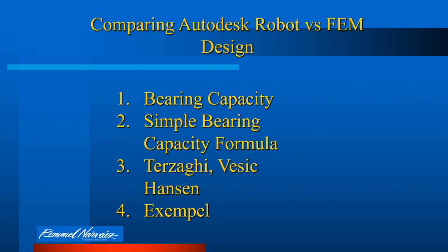To analyze spread footings for bearing capacity failures and design a way to avoid such failures, we must understand the relationship between bearing capacity, load, footing dimensions, and soil properties. So we are going to look at these blue points about bearing capacity: the simple bearing capacity formula, Terzaghi, Vesic, Hansen, and ensemble.